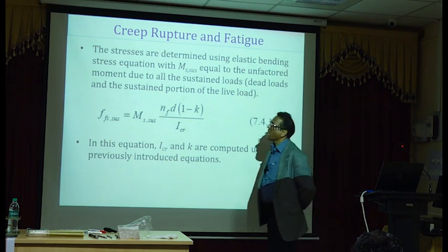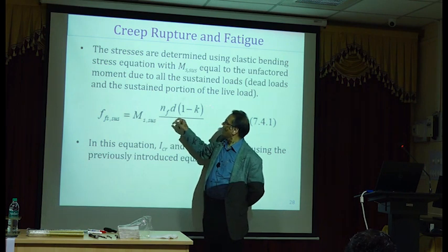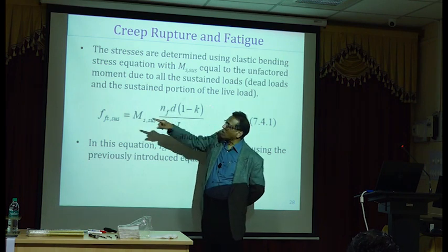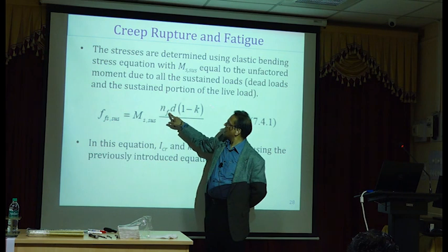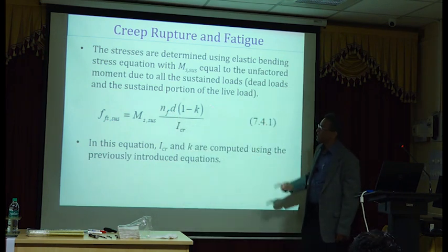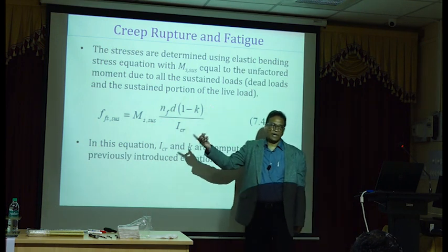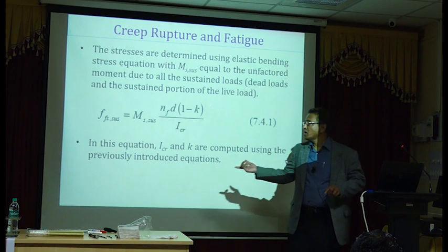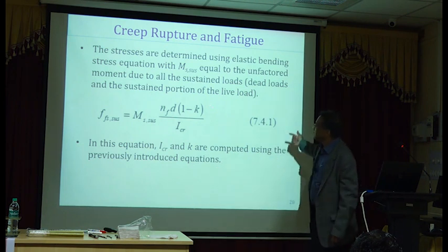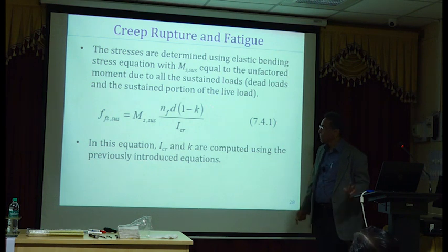So you have to calculate the amount of sustained service load moment, times Nf, the modular ratio, which we have defined there, times d times 1 minus k. k we already calculated from our previous slides, and then I sub cr, we already calculated from our previous slides. So this is what will give you ffs, the stress under sustained load.